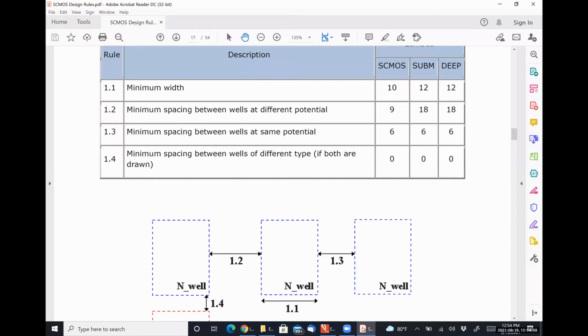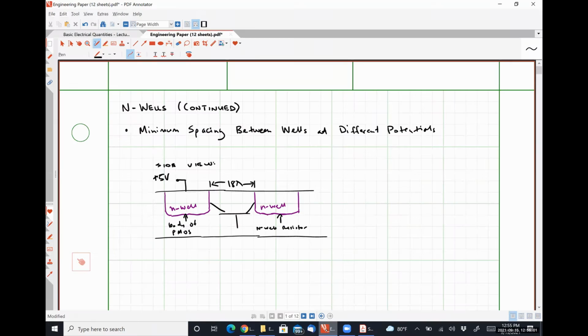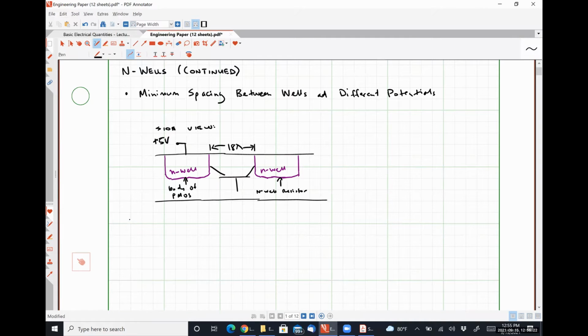All right, so now that I have introduced the concept of parasitic elements, right? Parasitic transistor, pretty easy to avoid. In fact, you'll get errors telling you to change the spacing if it thinks it's going to happen. Parasitic diodes are another potential issue. And these cannot be avoided per se by a simple change in the physical dimensions of the N-well. Okay.